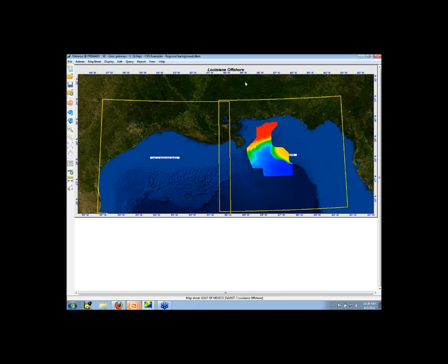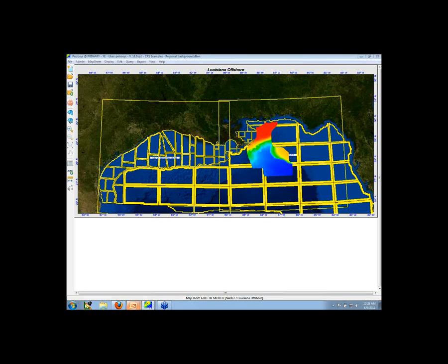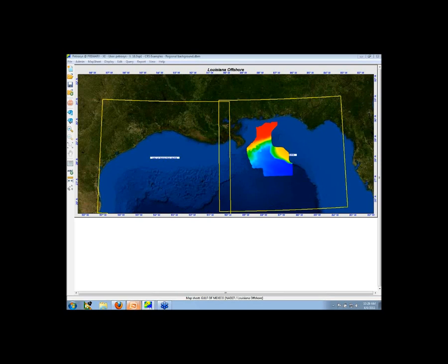So right now we can see I've got this WMS image, which is being projected from just WGS 84 latitude longitude values. I can also put some spatial data, so I can put lease outlines or protraction areas on the map. These are all going to be displayed from a NAD 27, and they're all being projected into this regional Louisiana offshore projection system.